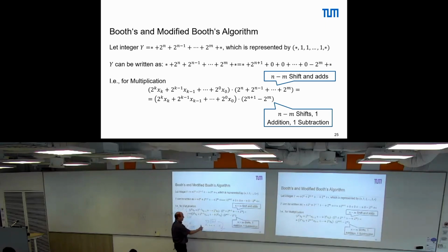So if I say I take just 2's complement numbers, what I do here is correct. I do not have to do anything. So that is already fine. We just need to keep in mind this number is a 2's complement number. The first bit is a sign bit. So effectively, here I should have written formally a minus 2 to the power of 6. Because it's 0 times minus 2 to the power of 6. Here we have plus 2 to the power of 6, of course.